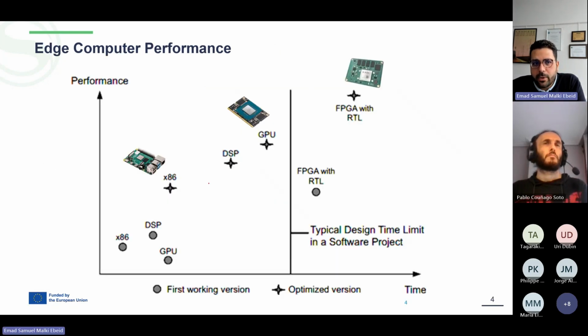A little bit about the onboard computers, and here it depends on the skills, and I will share with you my knowledge. If I speak about a Raspberry Pi, so I speak about a short development time. Let's say maybe a couple of days, you can get it up and running in a Raspberry Pi. Performance speaking is quite low.